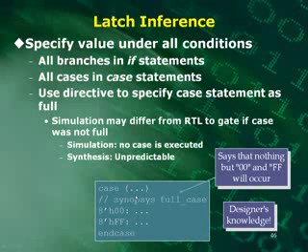Just be sure that you specify the value under all conditions. So that would be all the branches in the if statements, all the cases in the case statements, and use a directive to specify case statement as full if you need to. You can also put a default statement in. I didn't put that here. I should have done that. You could put your default statement in and make sure it gets a particular value. And just keep in mind that the simulation may differ from RTL to gate if the case was not a full case statement.